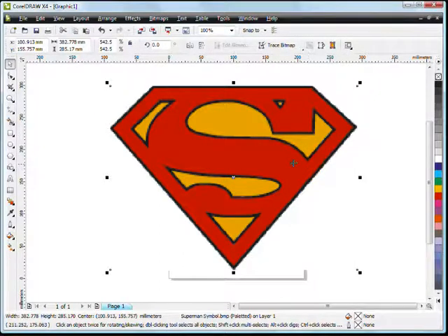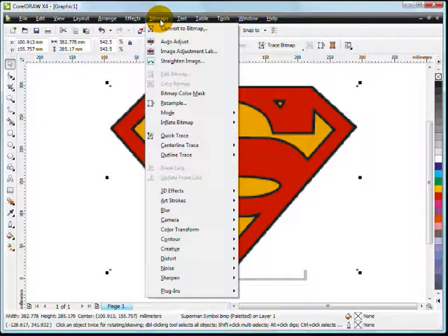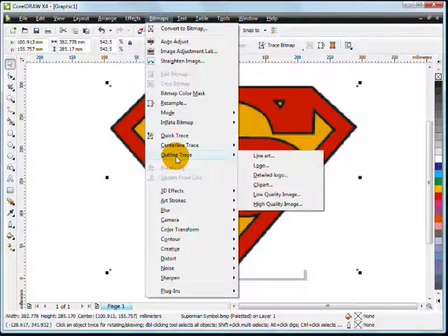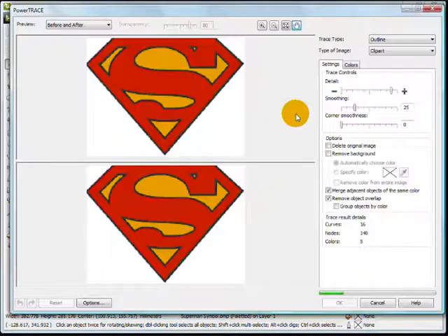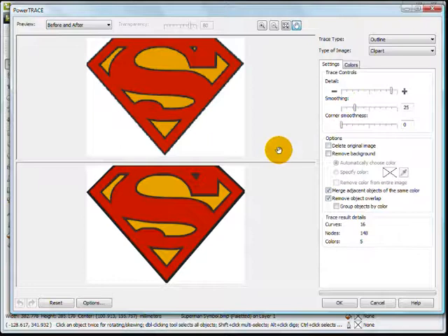So what we need to do is to trace it so that we can effectively convert this image into lines and coordinates. In Corel X4, they have integrated a tracing mechanism, so we can trace this. We go to Bitmaps, then Outline Trace, and then Trace by Clipart properties. Use this 90% of the time. The default parameters set for the clipart properties are generally pretty good, and you won't need to do much changing or adjustment of any of these functions.